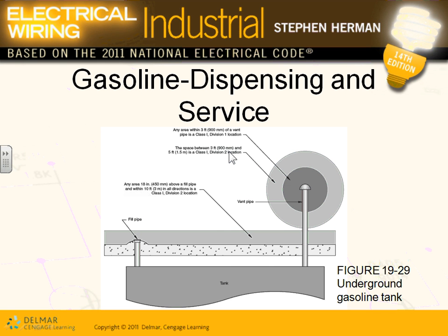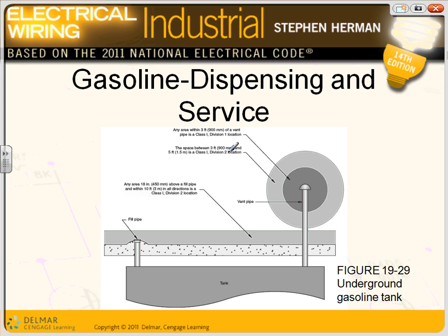If you have gasoline dispensing equipment, guys, you have the vent. There are a couple of places where you can have a vent. If you look at the dark one, up to 3 feet from the vent where they vent the tank, that's Class 1 Div 1. And then from 3 to 5, you see the first circle is Class 1 Div 1. The second circle around the first one is Class 1 Div 2. This one is 3, and this one will be another 2 feet, for a total of 5.